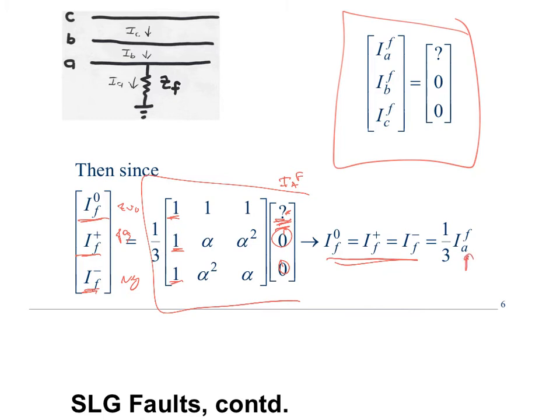So if I was doing a circuit, think about this from a circuit's perspective. If I had a 0 sequence diagram here, and I have a positive sequence diagram here, how could I make sure the current flow in this one is the same as the current flow in the positive sequence diagram? What if I connected them in series? Wouldn't this current be the same as this current if I connect them in series?